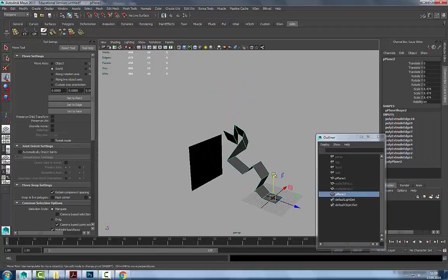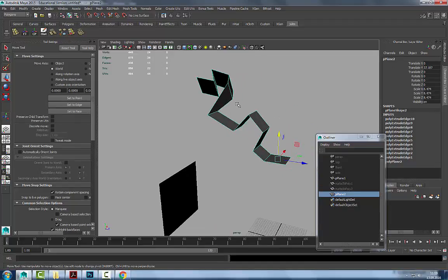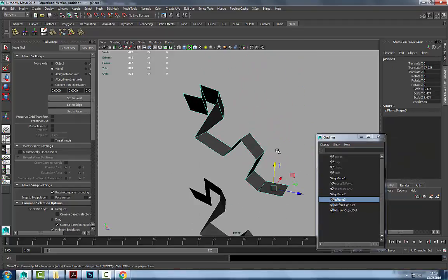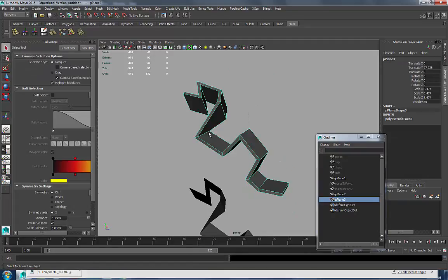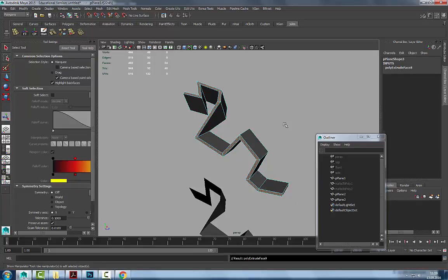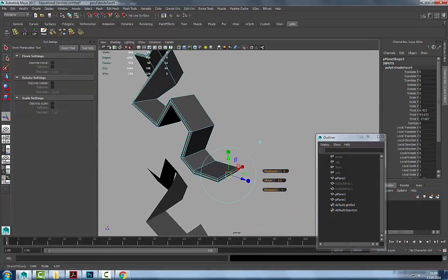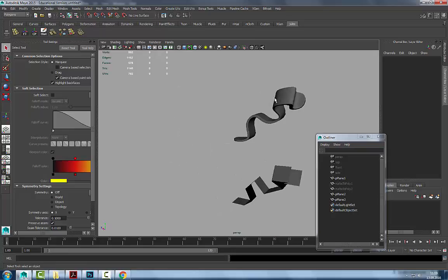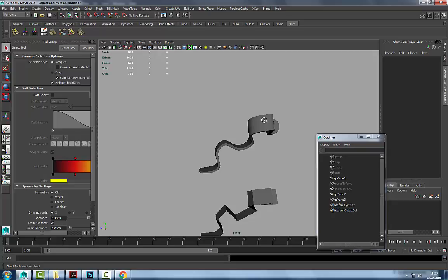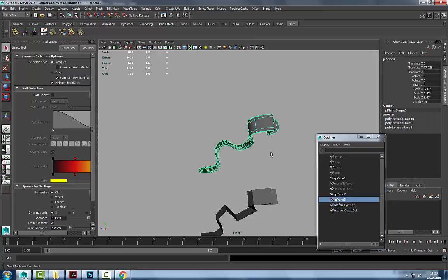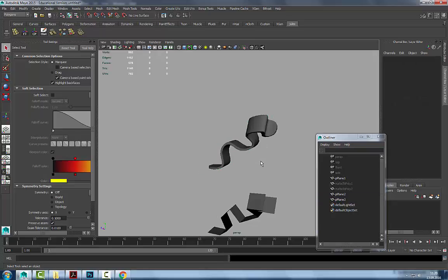If you wanted something like this to have thickness, just in object mode, do the thickness. You get a very nice uniform thickness, and then I can grab this face path and extrude it. Do a little offset, a little thickness, and a little offset, just to get those creasing edges. So we get this shape, which is very hard to achieve if you're starting out from a cube, because it's much harder to get this uniform thickness all the way throughout.